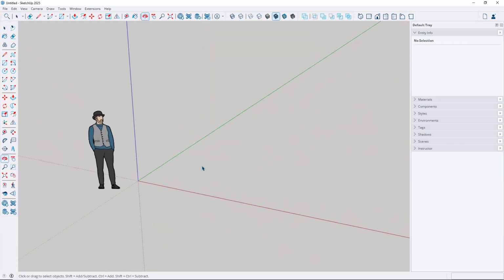All right. A little bit more on the interface before we draw anything. You see on the screen, you have 3 lines, and these are the axis in SketchUp. So this red axis right here, well, first of all, where they all meet, this is basically that point of origin. That's that 0, 0 starting point, similar to what you have in AutoCAD and other programs. That's an origin point. And you'll see how the line is red moving away from that point, and then it's dashed as it moves in the opposite direction, which is the negative direction.